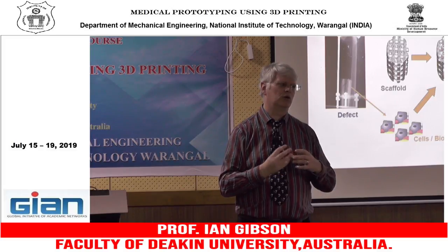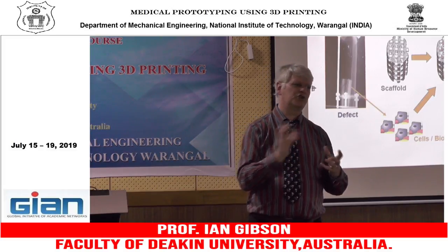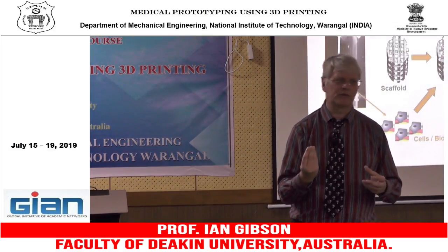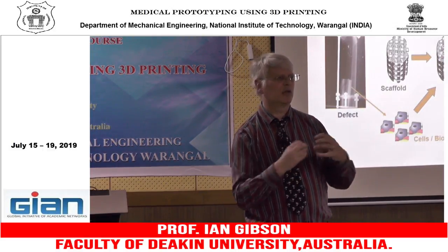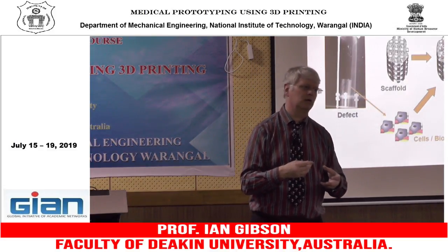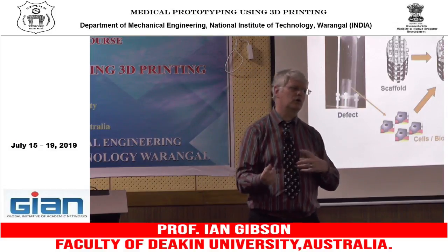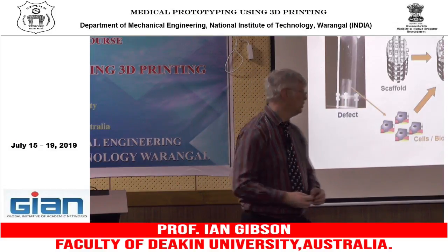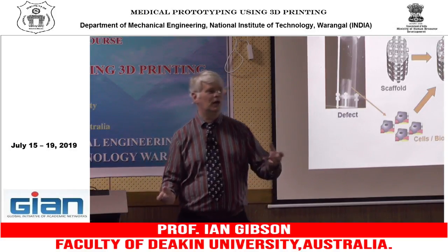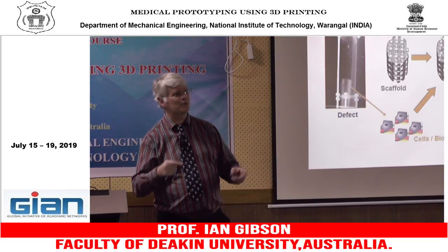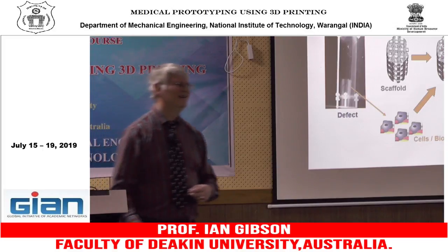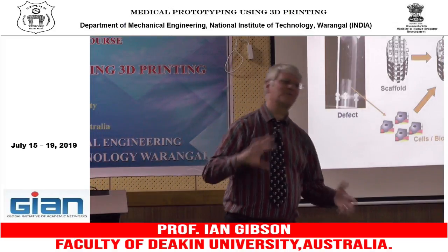Some of that you can address using additional additives like what they call surfactants, which activate the surface of the ceramic, sort of etch the surface, which allows for better blending. Another might be a cross-linking mechanism to help cross-link between the ceramic and the polymer. So these are things that we've experimented with. All bearing in mind that if you use these materials, they also have to be biocompatible. Okay? So this becomes problematic.